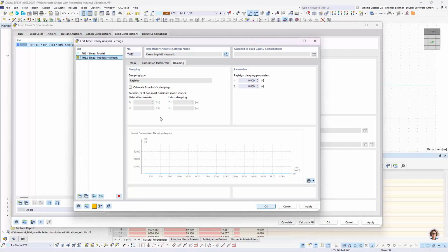And the sad thing, or the thing that sometimes occurs in some problems, is we have to use our Rayleigh damping, so our stiffness and mass dependent damping. We can use two frequencies to calculate those dampings. So we will go also here with 0.01 and here with 0.01.